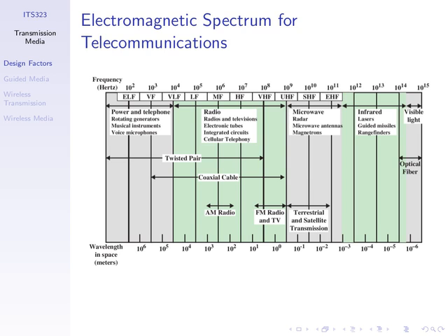And what we see on here is some examples. So some of the things that we know, this is the visible light portion of the spectrum. So the light that we see is transmitted in this range of frequencies. Note that this is a logarithmic scale, which means that the bandwidth available in this part of the diagram is 10 times larger than the bandwidth available in this part. So in fact, there's a lot of bandwidth available in visible light. Even though it looks like it's only one small part, this is much larger in terms of frequencies available, or bandwidth, than here, and especially down here.